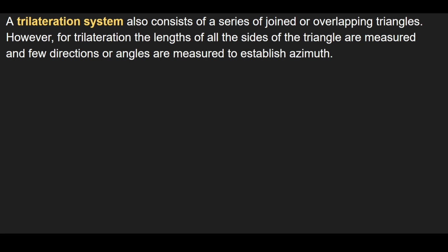So, before electronic distance measurement instruments, for example, the total station, so before the invention of that instrument, triangulation was mainly used because it is very hard to measure long distances accurately because historically you have to use the tape, right? And there are many errors that can come when you use the tape. Okay, so after the invention of EDMs, then we can use trilateration along with triangulation.